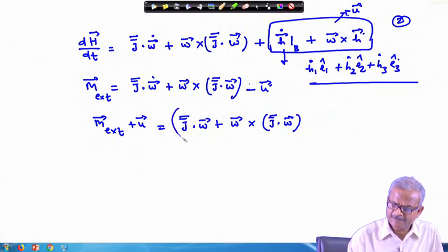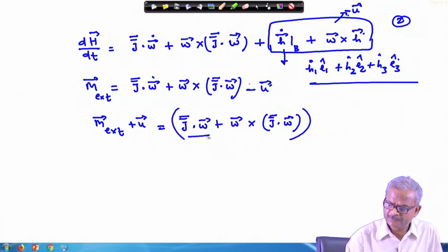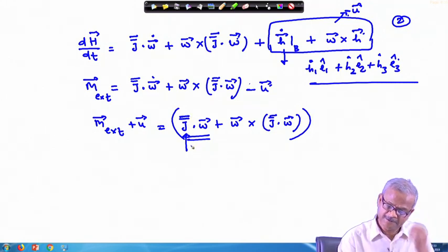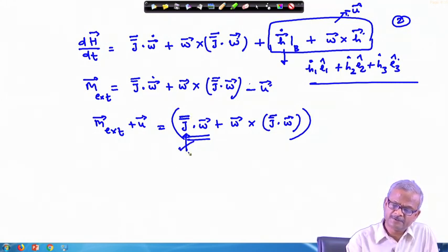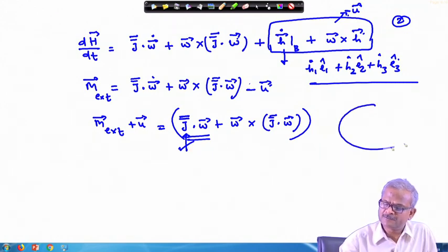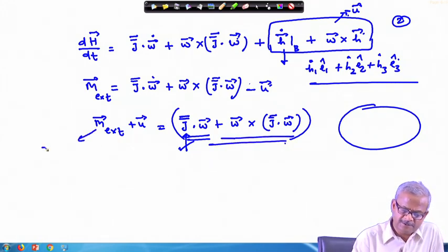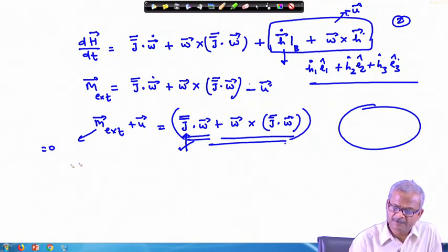So, in this context, how it is appearing, this is your whole satellite J double dot, this includes J double bar, which is the inertia dyadic, it includes also the wheel inertia. Okay. So, this is as if this whole satellite is rotating. For this you have written the equation, but what is the modification? If this quantity is 0, it is free from the external torque.